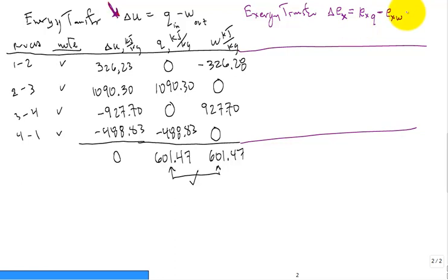And the other term is we could have some exergy destruction during the process. Well, what's the cause of exergy destruction? Well, the cause of exergy destruction are irreversibilities. So this exergy destruction term you might think of as T naught times the sigma, let's say, entropy generation during each of these processes. Well, we're studying the Otto cycle. The Otto cycle is every process is reversible. Hence, guess what the exergy destruction is for each of these is 0.